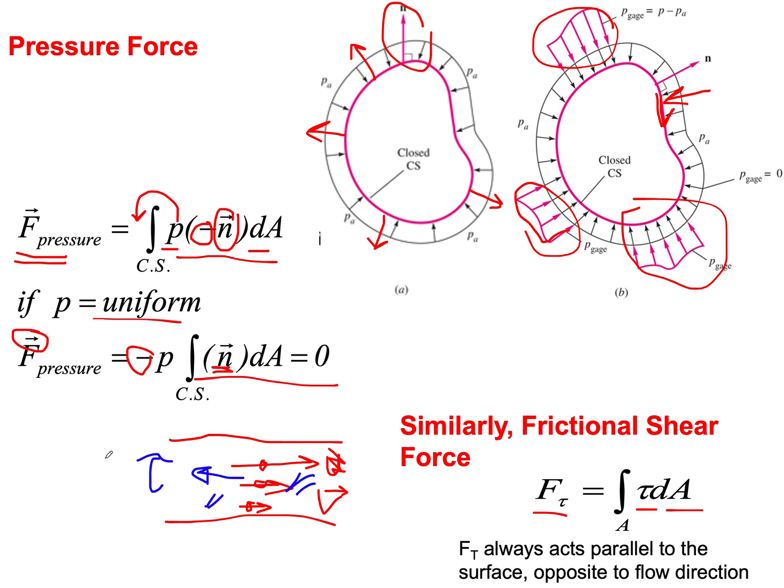So that's the shear stress and velocity. Now let's take another case, the same case. The velocity is acting in this fashion, and that's the only component of velocity that exists. Because shear is parallel to the velocity, I would not have in this case shear that is in the y direction, just because all the velocity is in the x direction. So in this case there is no shear, while in this case the shear is parallel to the velocity. So keep that in mind. This is a new concept that we haven't considered in the past, so take a moment to let that sink in: shear stress is parallel to the direction of motion, as you've been familiar with in your dynamics course and other courses.